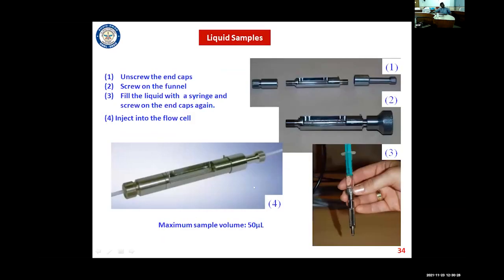And as I mentioned, we can determine the powder particles in the nano range. If the particles are in the nano range, they are chemically highly reactive, and then they form agglomeration. In order to prevent the agglomeration, we keep the nanopowder particles in some kind of solution, it may be acetone or glycerol, where the particle should not interact chemically with the solution. Then the particles are subjected to ultrasonic vibrations, which basically prevent the agglomeration.